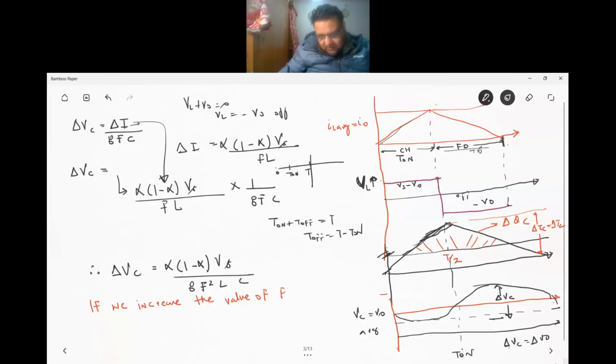So your charge was storing in the capacitor, in this circuit. So it was storing, and this is releasing in the on period. So this is the triangle that you are forming. The area of this triangle is half into base into height, that is half into T by 2, and the average of the current, delta I by 2. That's what I got, Q.